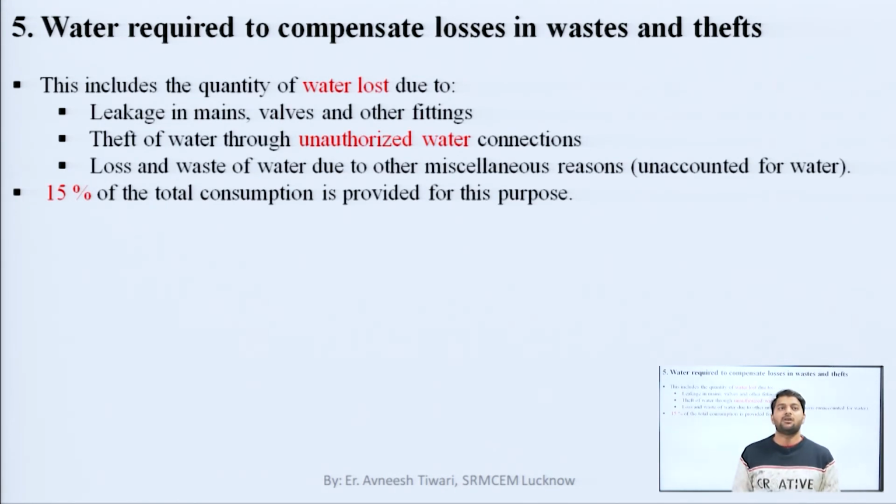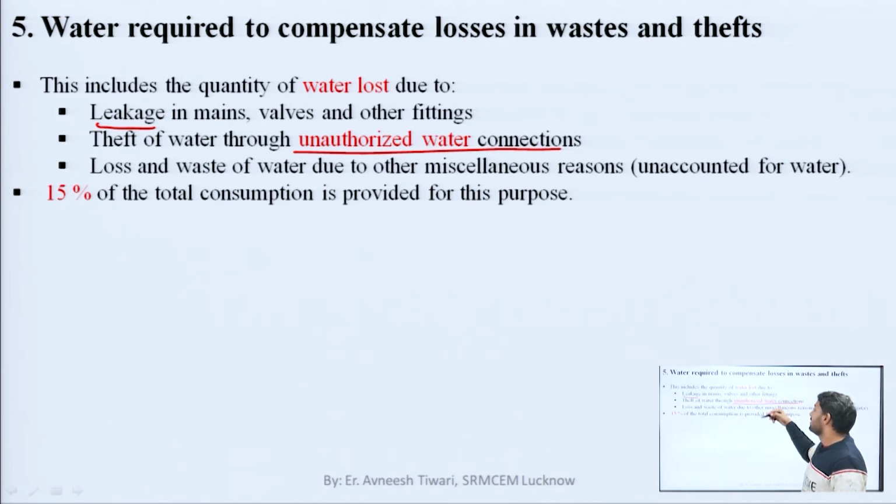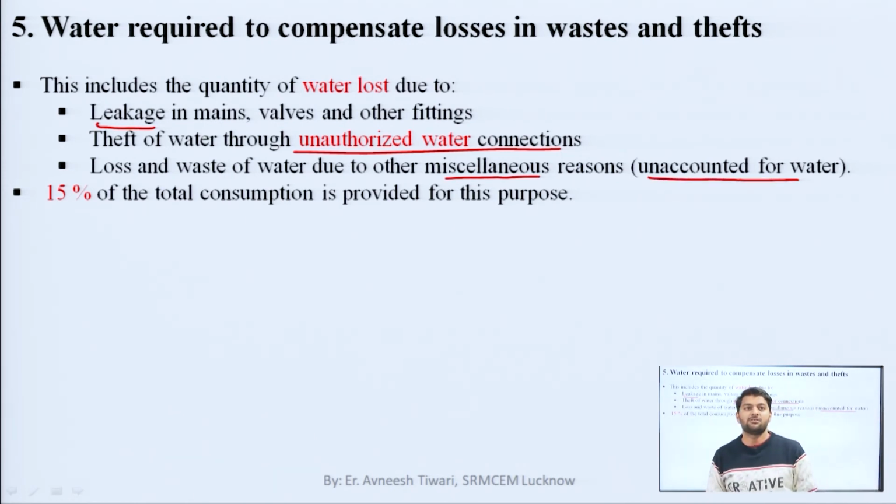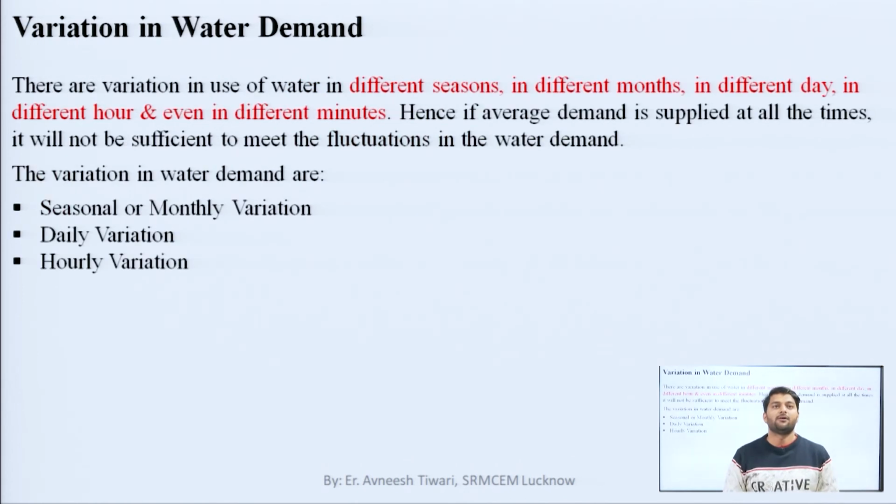The next one is water required to compensate for losses, and these are in the form of leakages, unauthorized water connections, and losses due to various miscellaneous reasons, and these miscellaneous reasons are unaccounted. For this purpose, we are going to provide 15% of the total consumption, of the total demand.